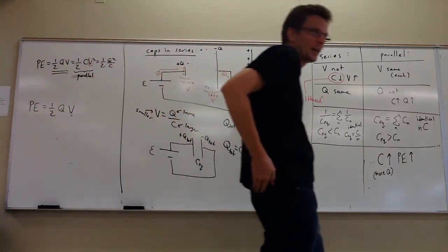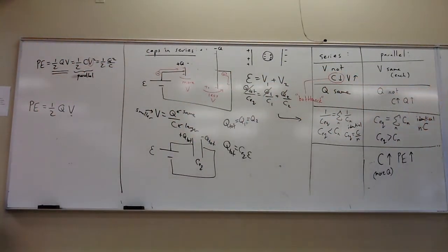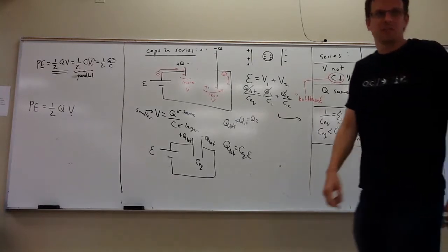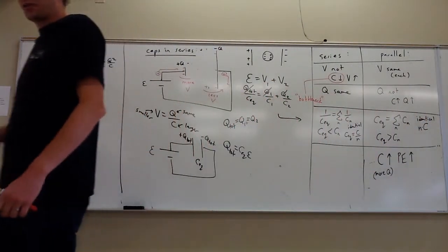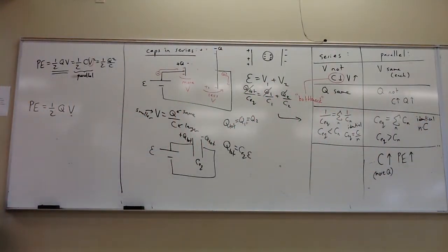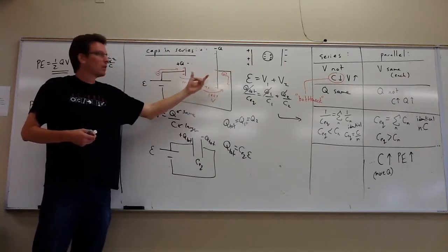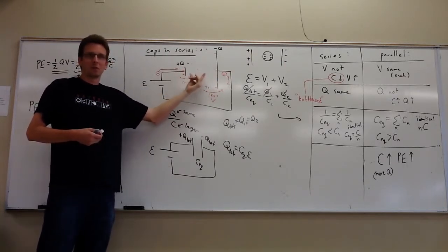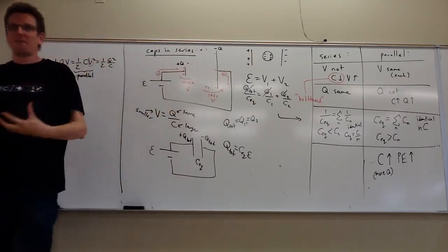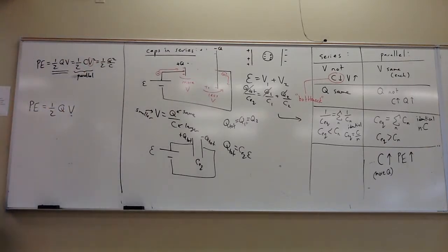So if you plug in capacitors in series, you actually get a worse storage device. How can you think of that conceptually? You aren't able to separate any more charge overall than they do individually, and of course you have to split the voltage drop between them, so you don't put as much effort into either one as you would if they were both connected across the battery terminals.